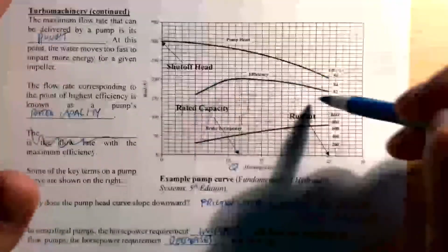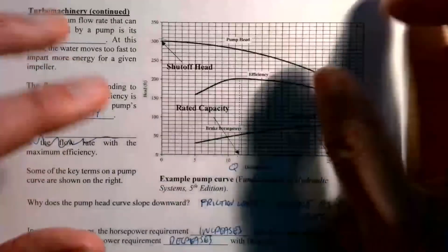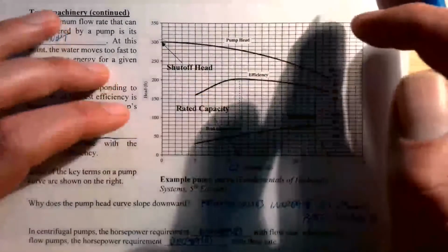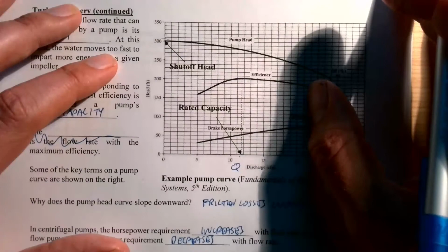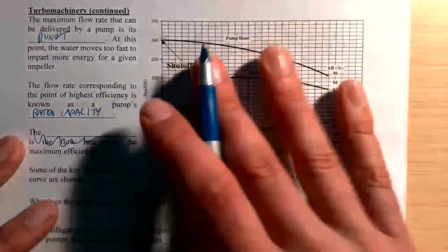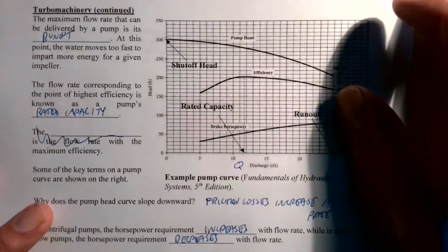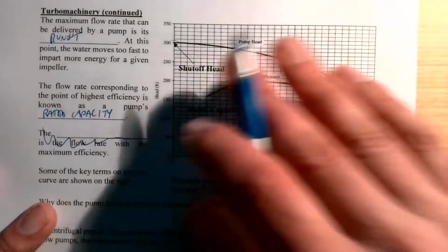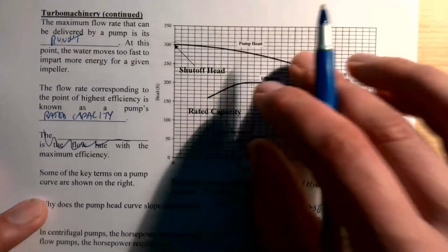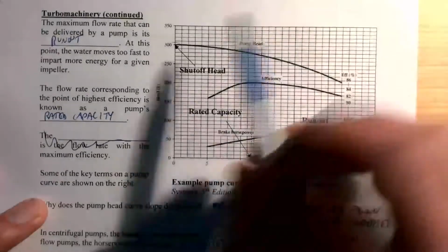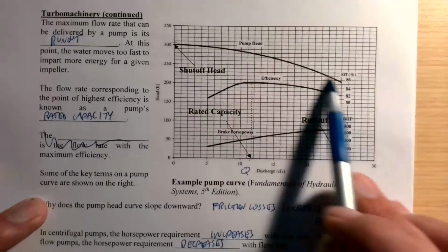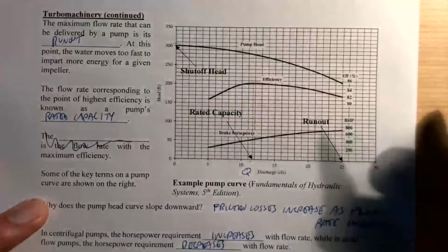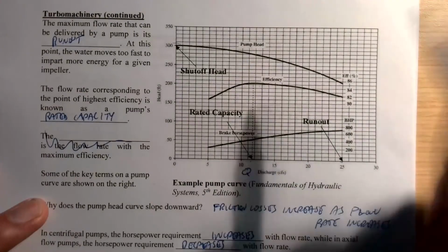In theory, you could fit a curve to these different things, and then you could do it without having to plot it. I would kind of like that idea if you could do it. But we're going to look at the traditional way, where we are plotting the system curve on here and using that to figure out what flow we would get. Okay, so remember, this is the energy supplied by the pump, and we're going to come up with a new equation, A plus BQ squared.